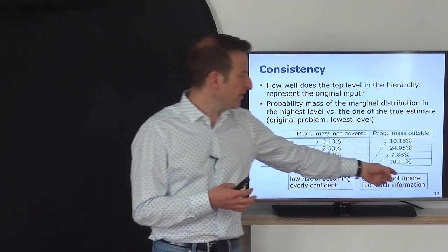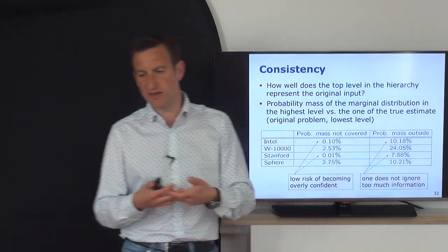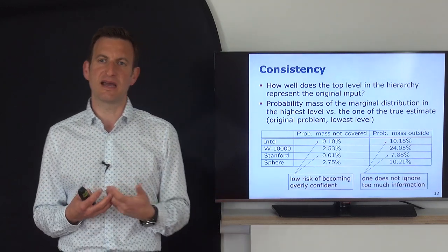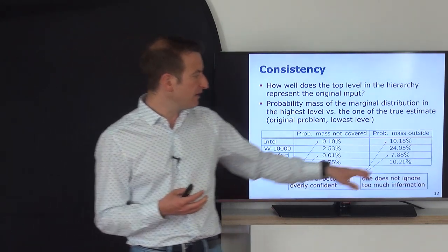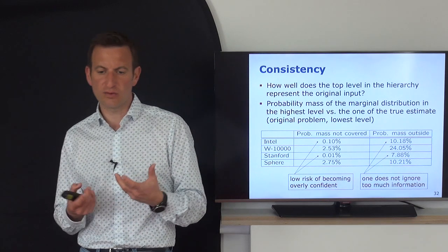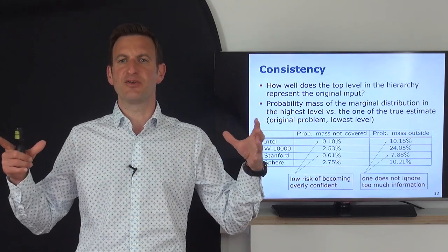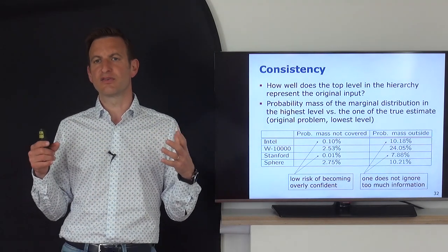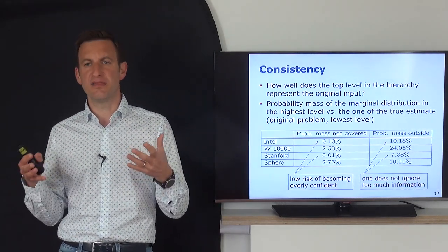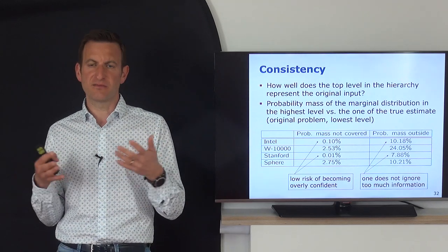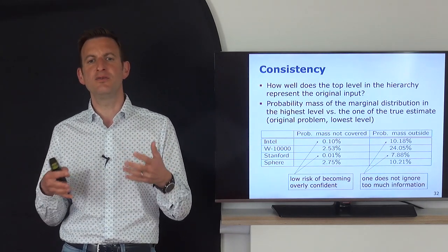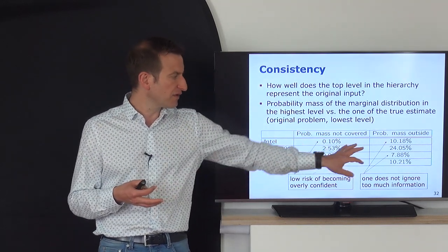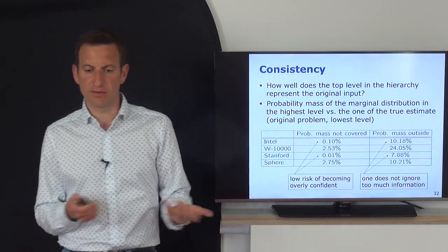And then there's the other case, where the uncertainty ellipses are too large on the higher level, so it's a higher uncertainty than I actually have in reality. And here the values go up to 25%, so some covariance matrices may be 25% bigger than the ones I would get on the lowest level. So I have a higher uncertainty on the higher levels, but that's typically still okay. I may need to check a few more nodes when I'm looking for loop closures, but at least I don't miss some. So this is less critical from that point of view.